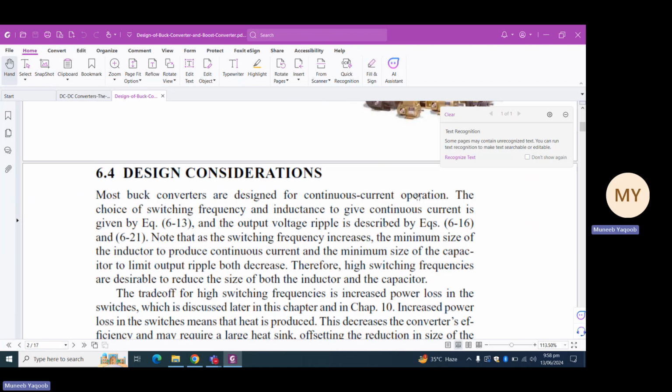One of them was that the capacitor is large enough that the output voltage is constant, or in other words, the ripple voltages are reasonably smaller as compared to the output voltage. So the ripples may be neglected. Similarly, we were assuming that the buck converter is operating in its continuous conduction mode, that is, the minimum inductor current is more than zero. So these are some assumptions that we make.